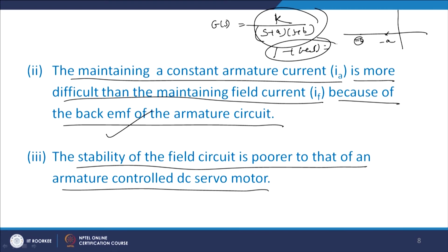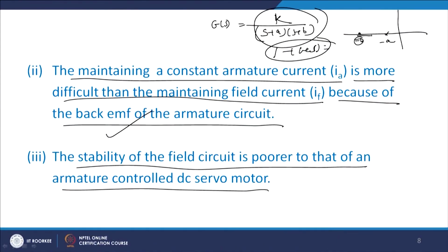So, for second order system we will find that, let us say root locus means the locus of roots of the closed loop characteristic equation when one of the variables, the gain k, is varying from 0 to maximum value or 0 to infinity. That part you might have studied in classical control. So, here I am drawing the root locus for this. There is a pole and there are no zeros, it will start from here, one is going like this, other is going like this.